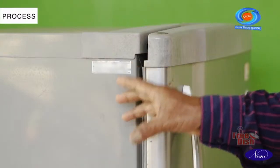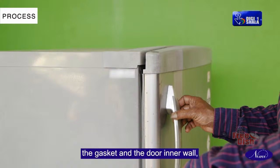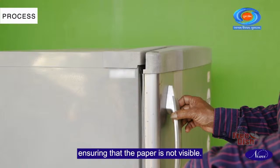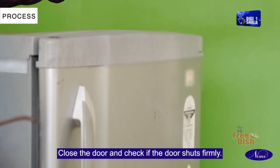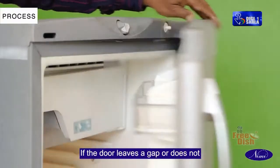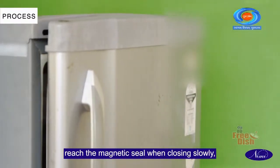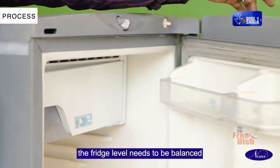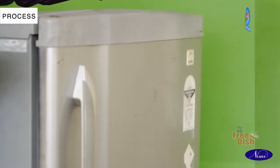Fold the newspaper neatly and insert it between the gasket and the door inner wall, ensuring that the paper is not visible. Close the door and check if the door shuts firmly. If the door leaves a gap or does not reach the magnetic seal when closing slowly, the fridge level needs to be balanced for automatic closing.